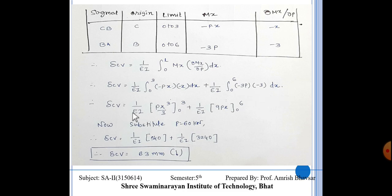So delta CV is equal to 1 upon EI, Px cube upon 3 with limit 0 to 3, plus 1 upon EI, 9Px with limit 0 to 6. Now we have to put the value of P as 60, so we will get 1 upon EI 540 plus 1 upon EI 3240. So finally after putting the value of EI, we will get the vertical deflection at point C, that is 63 mm downwards.